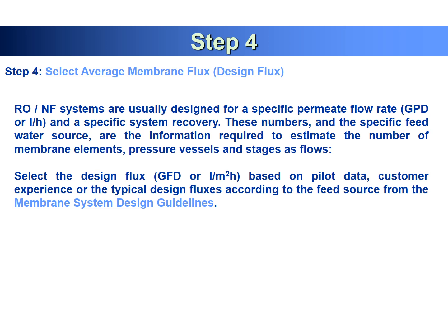So based on your water quality, we can select the element. This element also provides average membrane flux, which is different for groundwater, wastewater, seawater, and surface water, and we can select the recommended average membrane flux. This will be given by the membrane manufacturer companies. So each membrane has a recommended average membrane flux, and then we can select based on each desired membrane water.